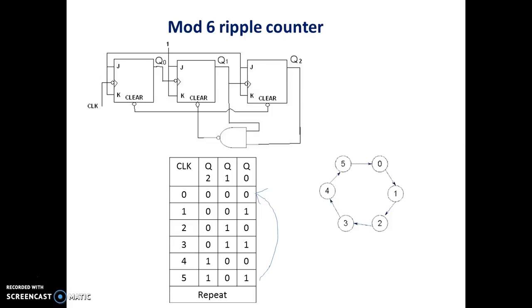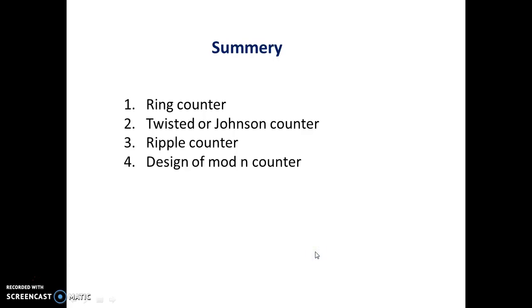So in this video lecture we have seen 2 applications of flip-flops, that is the shift counters and the ripple counters. Based on this, here is the summary. We have seen the ring counter, ripple counter, and we have also done the design of mod n counter.